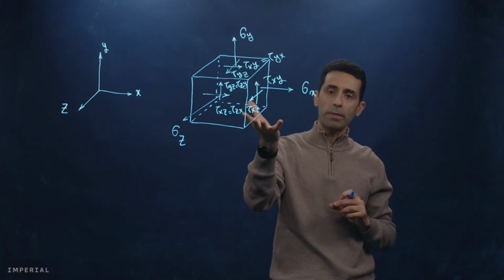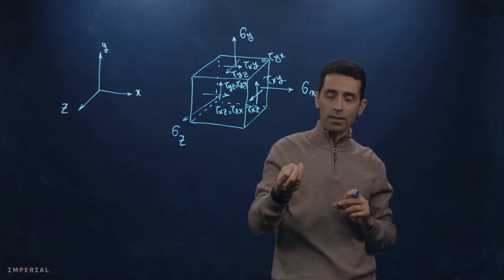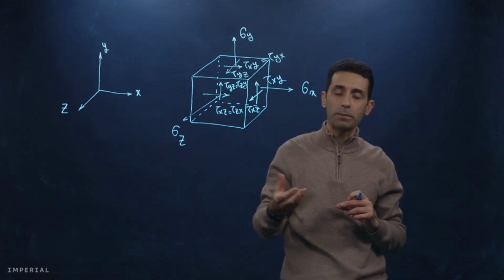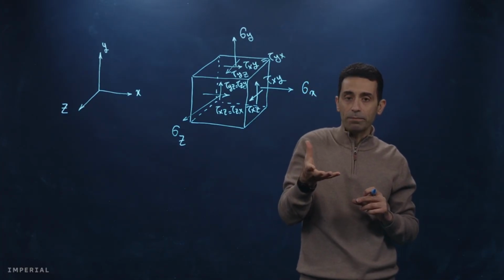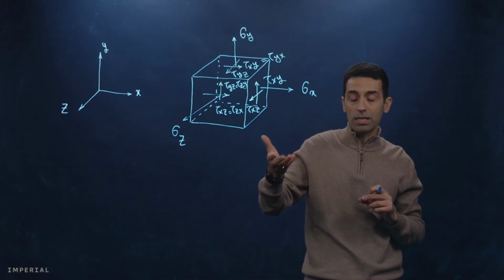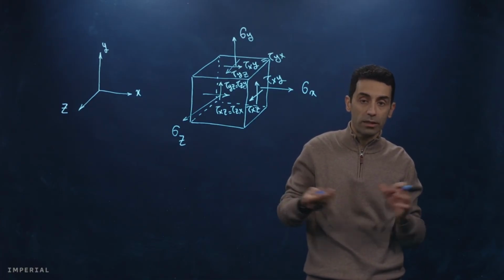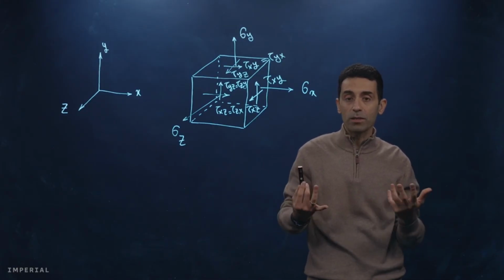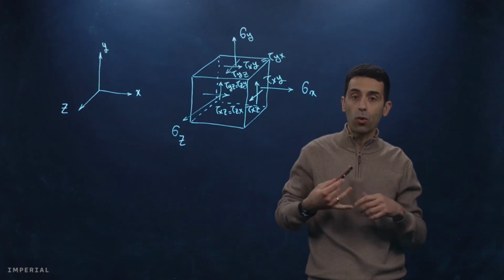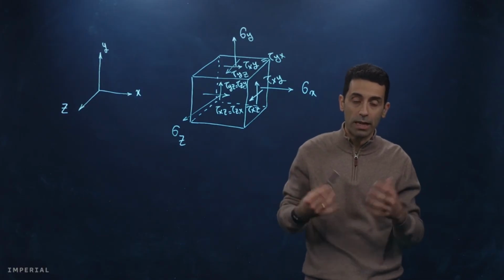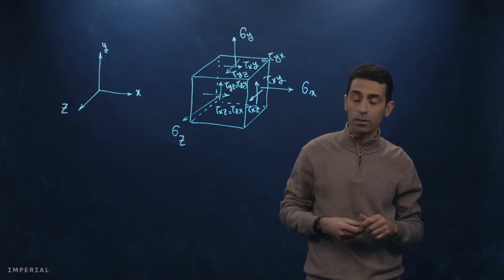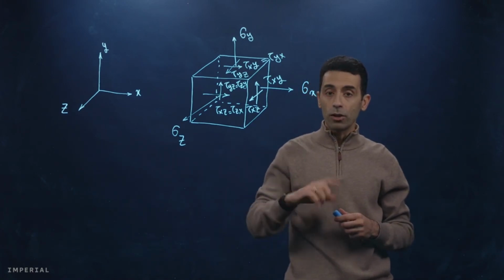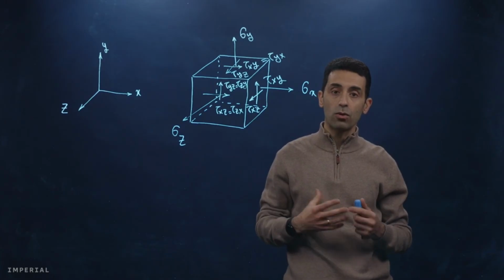This is called a tensor. Stress is a tensor. Tensors follow certain rules for transformation. A scalar is a 0th order tensor, like temperature. Vectors are first order tensors. Examples of vectors are velocity or acceleration or displacement vectors, and they have certain rules for transformation. Stress is a second order tensor. We are going to see another second order tensor, which is called the strain tensor.